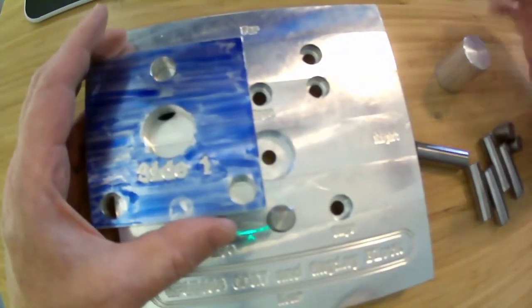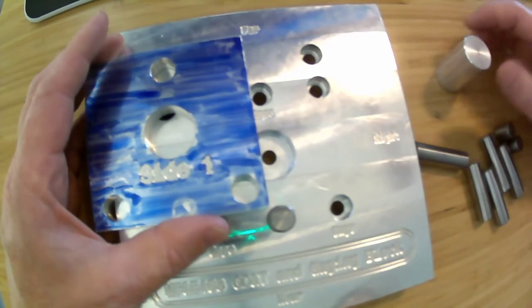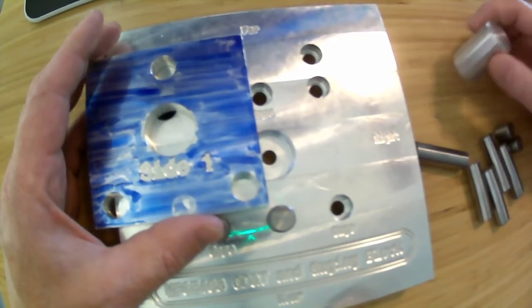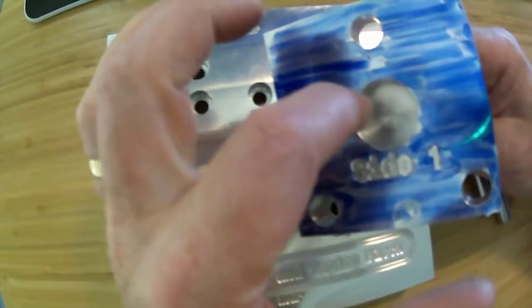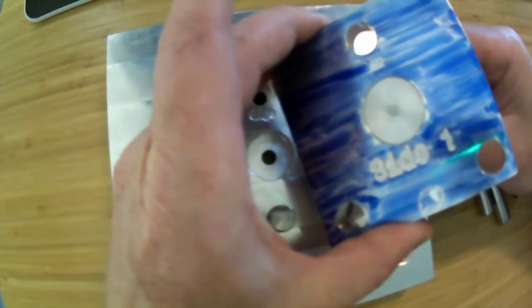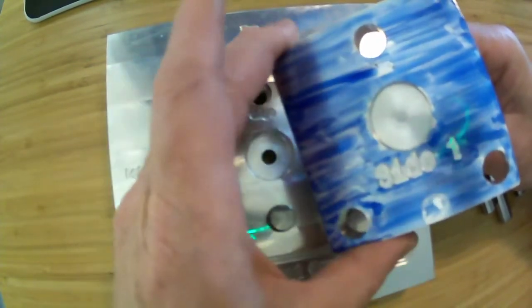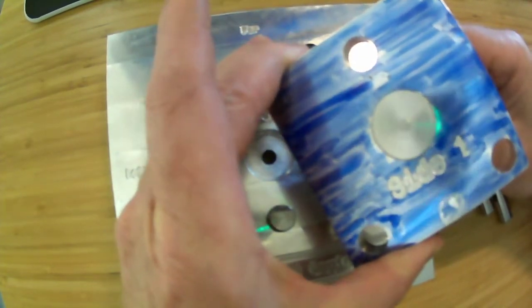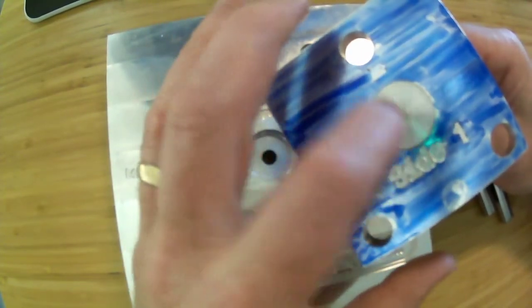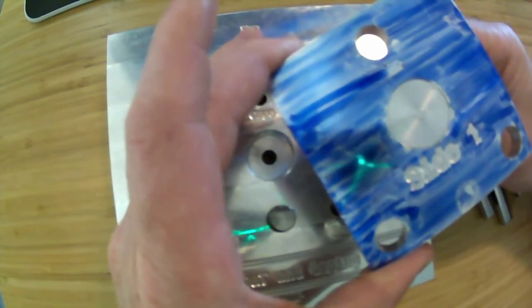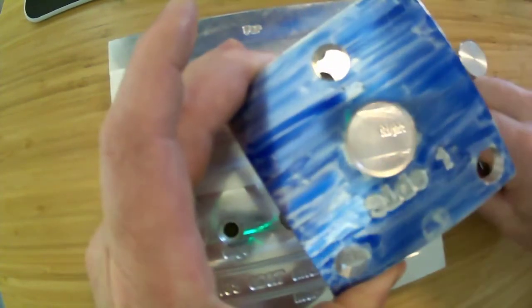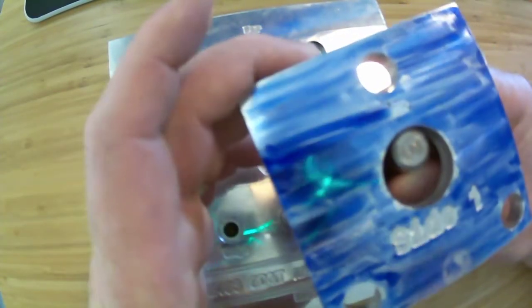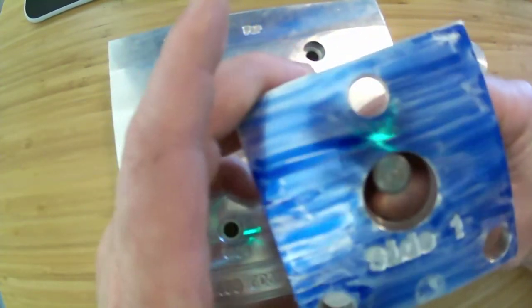Okay, so there are lots of options here and lots of things that I can do, and each of them contains some assumptions. How many degrees of freedom this removes, the pin in this big hole, depends a little bit on what the contact length is along the sides. It depends on how tight these two are together. If the cylinder were really small compared to the part, well, let's go to the end case, which is a little tiny cylinder.